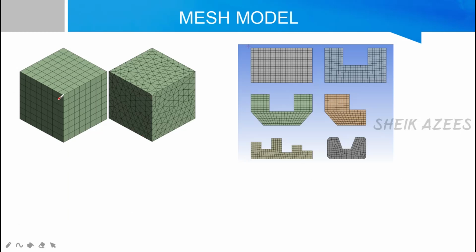So in this model you can see the square cube with a full tetrahedral mesh. Okay, it gives a perfect result because it has a perfect mesh. These are cubes, but here you can see tetrahedral, like a full of triangles. What happens here is it becomes abnormal. Here there is a chamfer, so the tetrahedral appears here. That means tris are coming here for 2D. Like that we have to mesh the model.